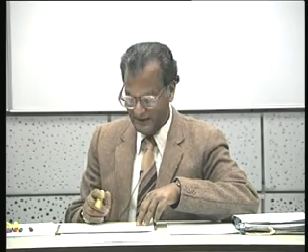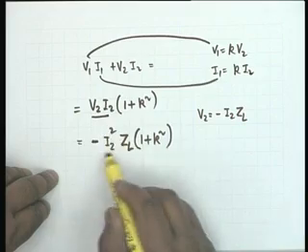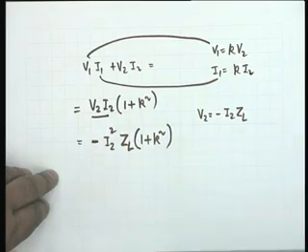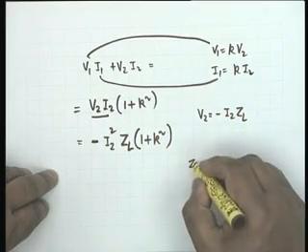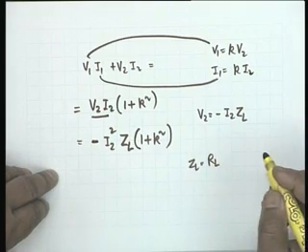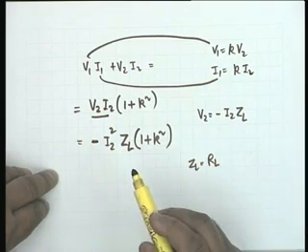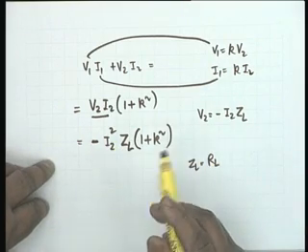Alright. Therefore, the power that goes in can be negative. I2 squared, if it is a resistive network, let us say if ZL equals a positive resistance RL, then I2 squared is a positive quantity, and therefore the power that goes in can be negative, which means that the 2-port generates power. It does not absorb power, it generates power.